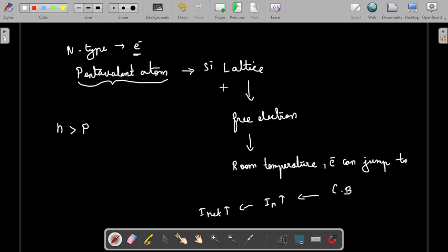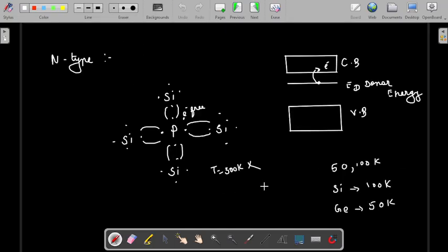I hope this is understood. I think this structure will give you quite a good understanding. This free electron is the key to everything. Okay, so next class let's discuss the p-type. Let's draw a lattice structure for p-type with a trivalent atom. Then you will learn about the effect of the majority charge carrier, which is holes, in the p-type material. The same thing happens there. I think this is how n-type and p-type materials are categorized and how the current movement is produced.